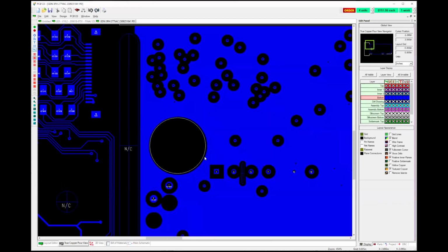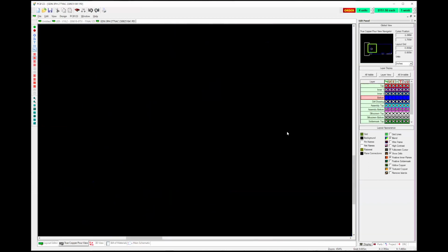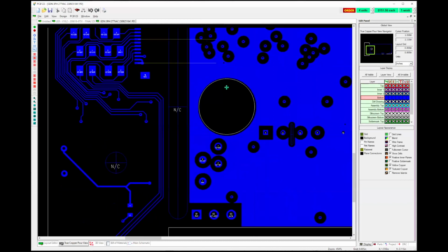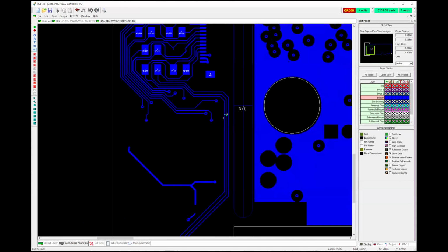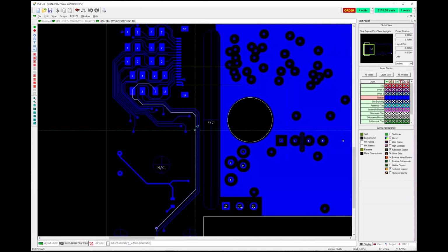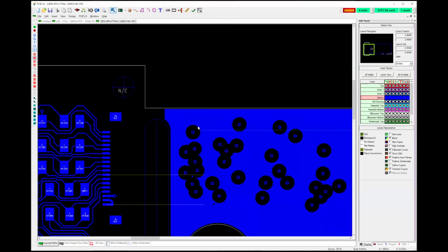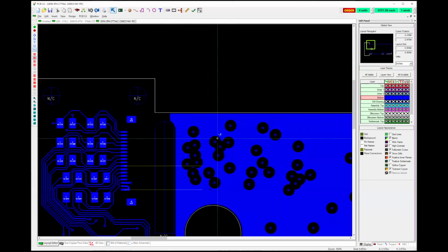So all of the clearances are in there, all the places where the clearances overlap, because sometimes the board that you're looking at in the actual layout editor may have features that are slightly different when the Gerbers are drawn. It's just part of the tooling process, and this takes into account what's going to happen with the tooling process.